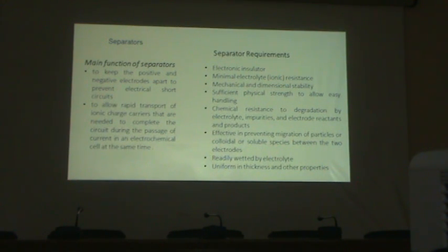People who work with lithium-ion batteries, if they have used Celgard separator with EC and other common solvents, will know that some salt and solvent combinations don't wet the separator well. You have to figure it out yourself before just taking the Celgard and making the cell. Yeah, you have to check it out. So normally we all start with glass fibers, that's the easiest option.